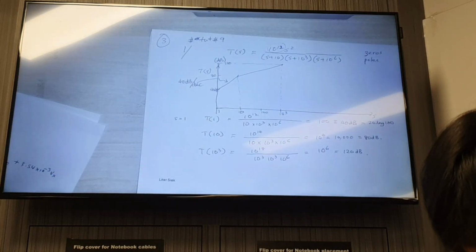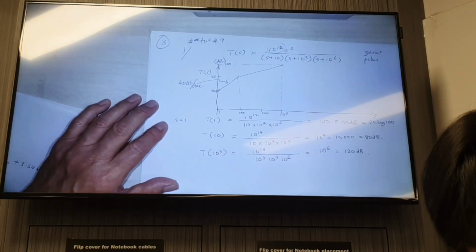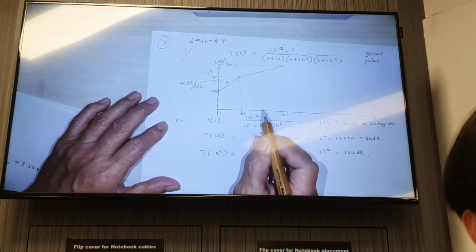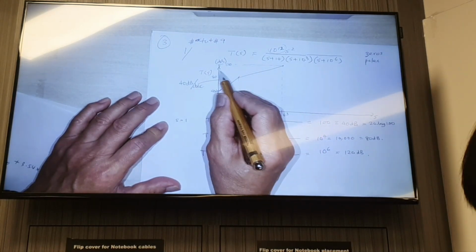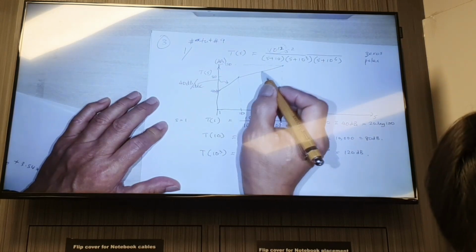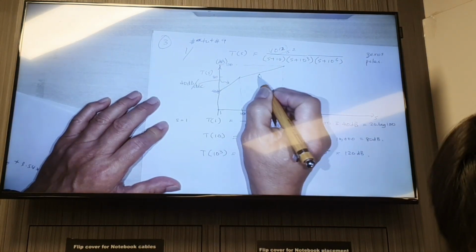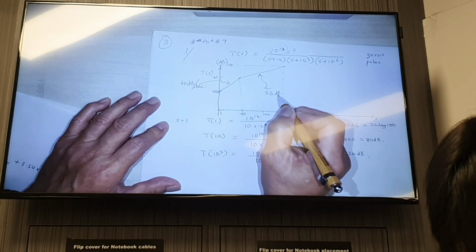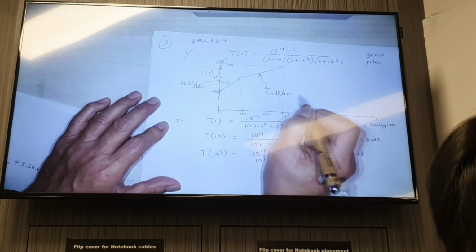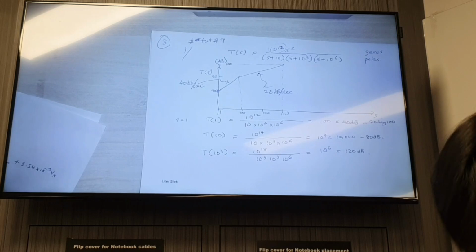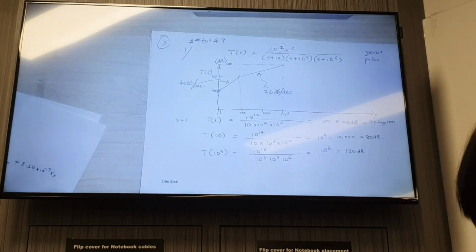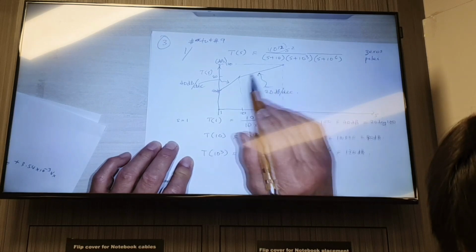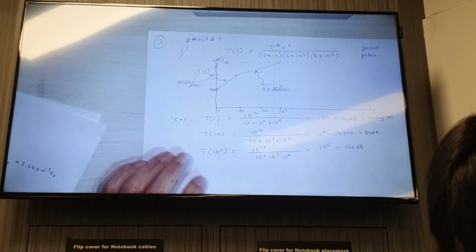So this tells you that in 1 decade, we would have gone to 100. So this slope here is 20 dB per decade. It's this kind of question, where you get the slope from the graph, like from the ABCD. In 2 decades you have 30, 40 dB. Then you try and calculate it, then you work backwards.